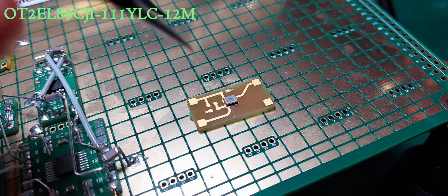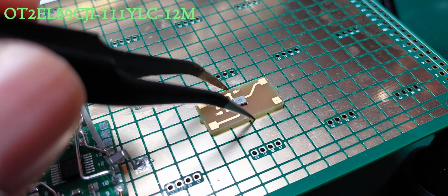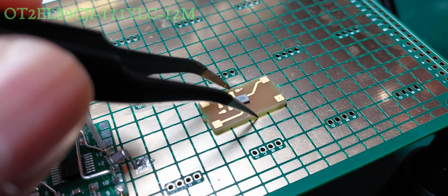I was lucky enough to find a low jitter crystal on LCSC specified to have an RMS phase noise of 0.7 picoseconds. In combination with the 74AHCT273D latch, it should clean up the PWM signals coming from the Pico, which has a measured jitter of around 70 picoseconds RMS, which contributes approximately 0.1 ppm to the INL. Unfortunately, this didn't seem to have much of an effect, but I decided to keep it just in case.